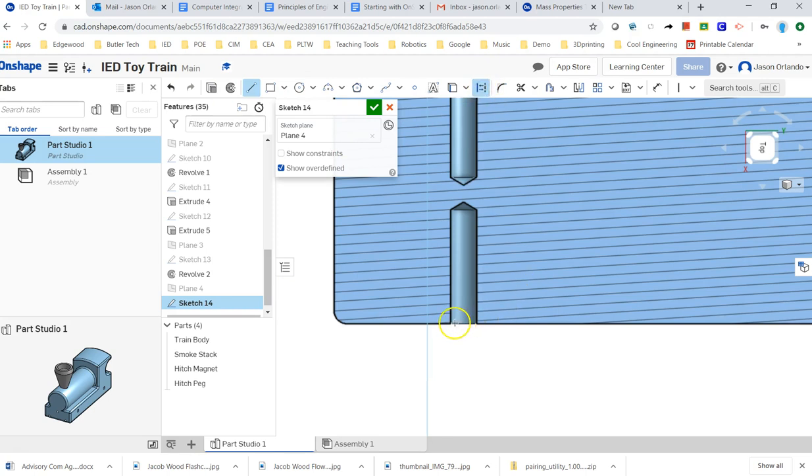That means it's going to be dashed, and it's not letting me find the midpoint right here, although it might allow me to use that point, right? And if I didn't have that, I could make a line extending across here, and then find the midpoint of that point and come out this way. But this right here is just giving me a reference line that I can find the middle of that hole pretty easily, okay?